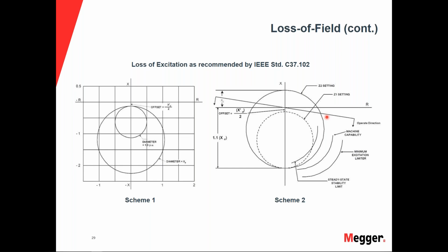When we use the typical zone 1, we're just going to have a very short time delay, if any, into this zone, but we're also using our zone 2 as our main time. So if our impedance comes into this zone, we want to give our operators enough time to be alarmed and try to get this resolved, or if not, watch it, because it could come into the zone, alarm, and it can also come out. So it's giving everybody in the control room an idea of what's happening and to be prepared if this does have a loss of field situation happening.